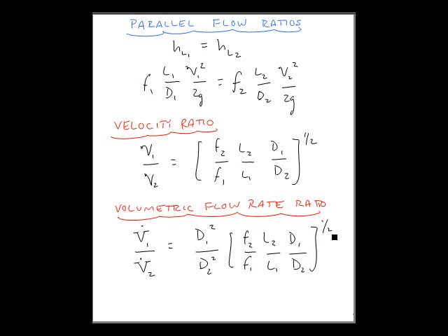Okay, so why do we use this? Well, we want the head loss to be constant because we said the pressure drop is constant. These could be nice ratios, velocity 1 compared to velocity 2. It's all dimensionless at that point, and so we can pull out what our friction factor would need to be, or what have you, if we know the ratio, or we're designing towards a ratio.